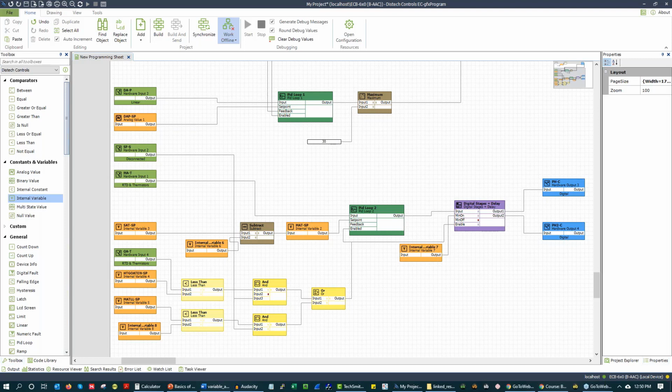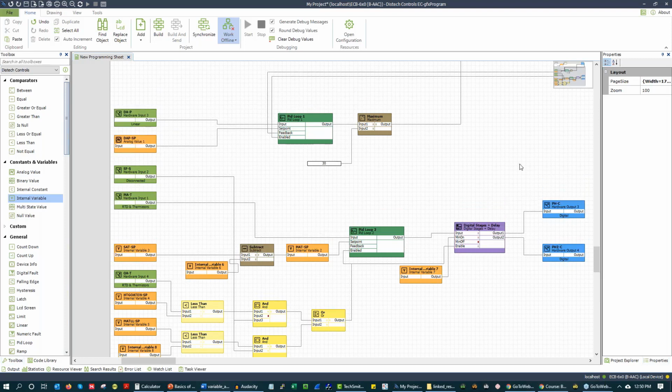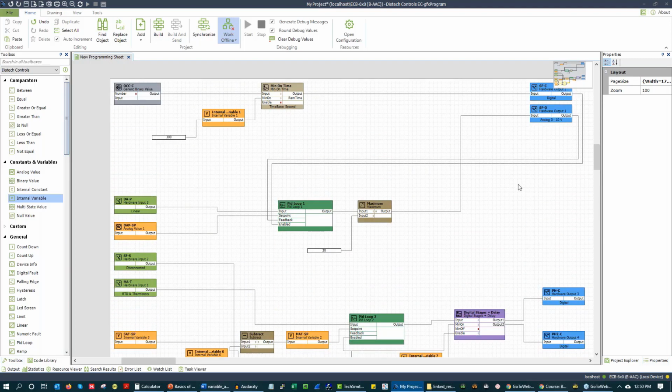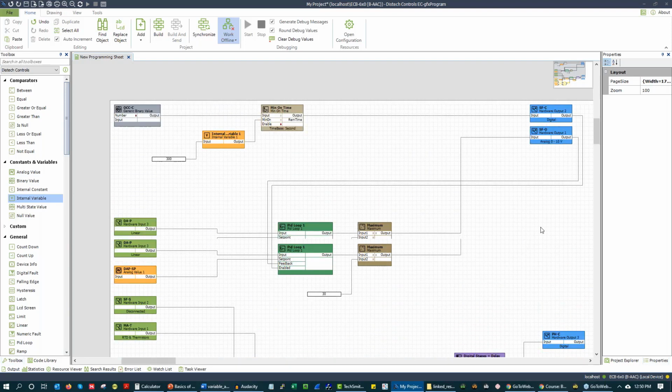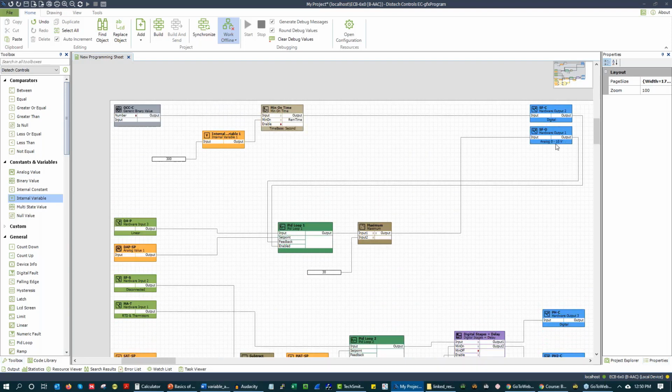So Ryan says, can I explain the feedback from the fan control back into the PID loop? Bit confused why we would need this. Okay, you've got Boiler Bob. And Boiler Bob decides that he is now Air Handler Adam. He has changed his name. And he decides that he's going to go up to the VFD on the controls, and he is going to override this output to 100%. Now, naturally, the VFD was calling for 40%, and it's like, hey, what the heck? I'm way overshooting my discharge air pressure set point. So the loop starts winding down and winding down and winding down. And next thing you know, the loop is negative in its calculation.